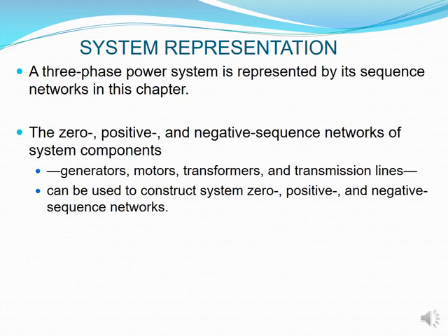So in this chapter, we are going to be looking at our three-phase systems where we have unsymmetrical faults, and we're going to see what really happens when our network splits into your zero, positive, and negative. I'll mainly concentrate on the zero, because on your positive, I'll show you how we can do it, and then you just need to put in a generation source, and your negative is usually drawn just like your positive, except it doesn't have that generation source.